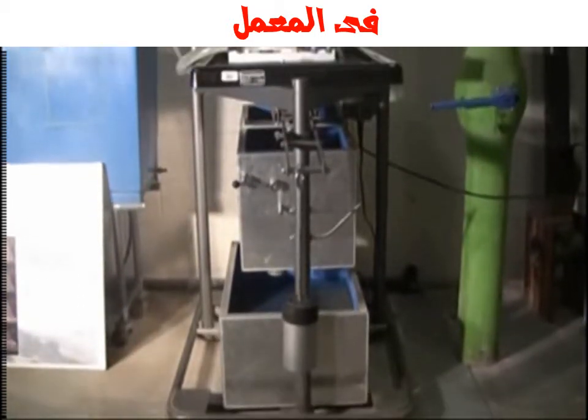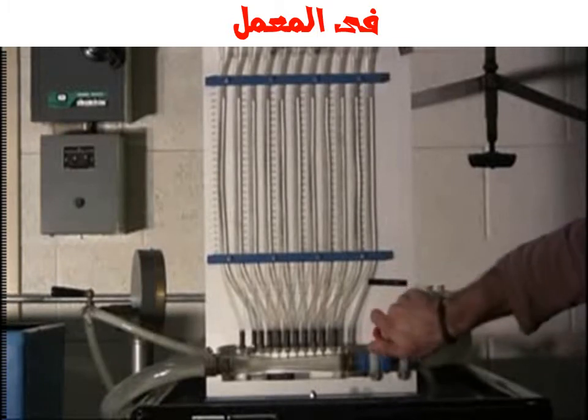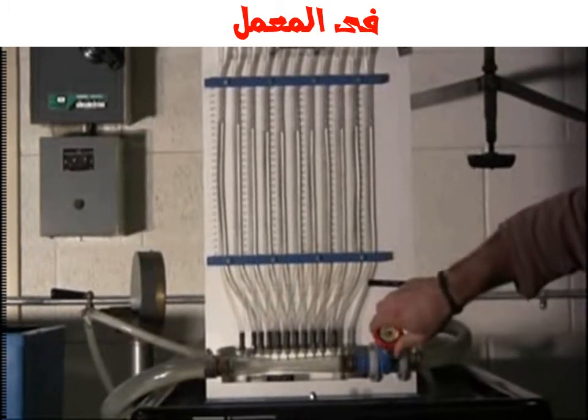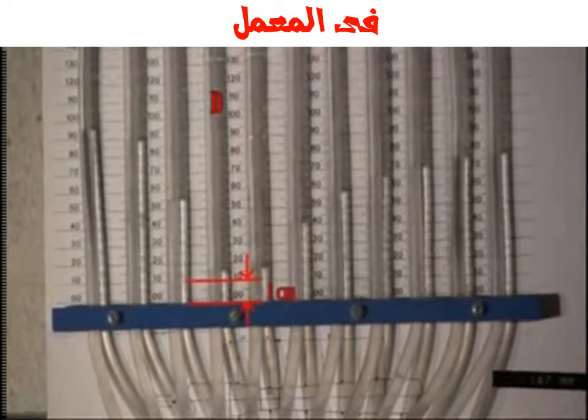Going into the procedures of this experiment. First, set the flow at maximum capacity by opening the regulating valve slowly. This is obtained when the lowest piezometer reading is about 1 centimeter. This should correspond to the reading of the piezometer at station D.